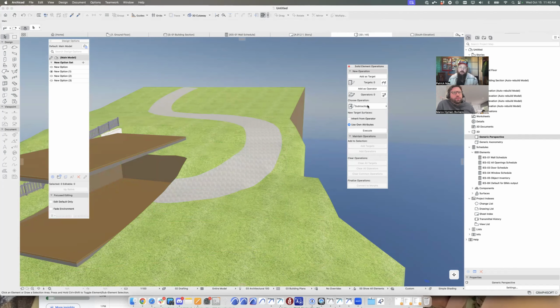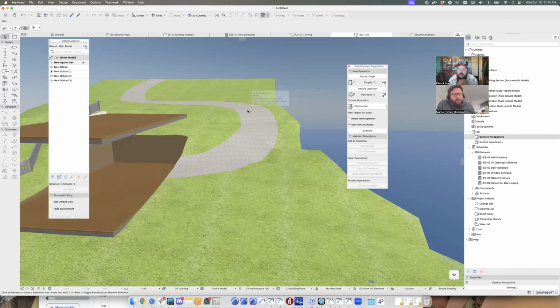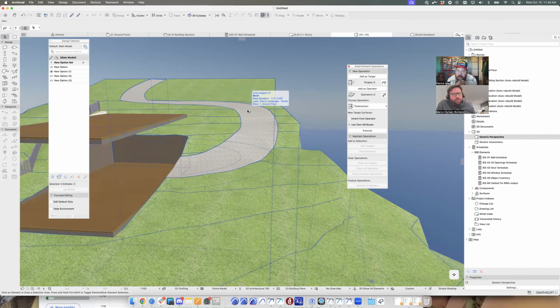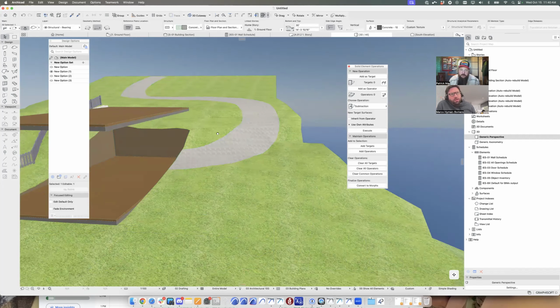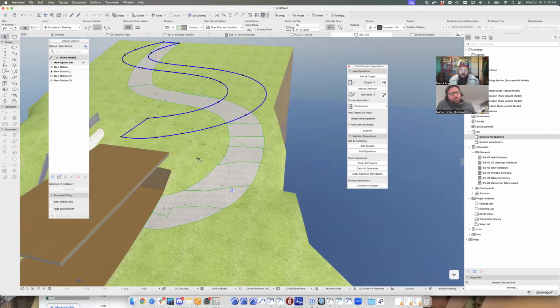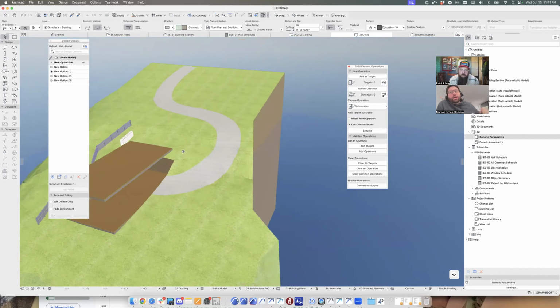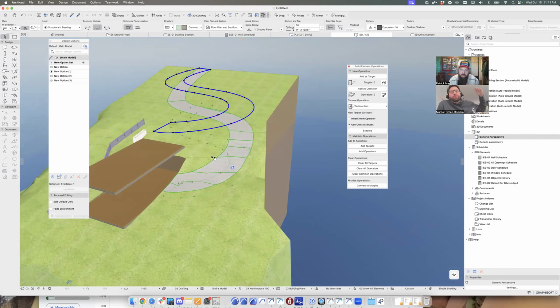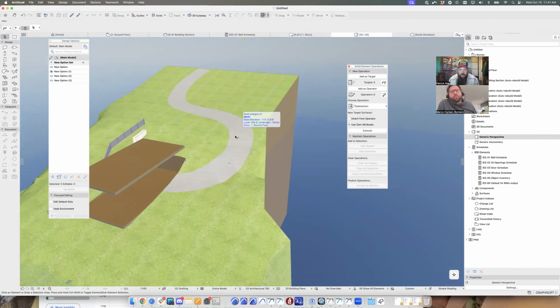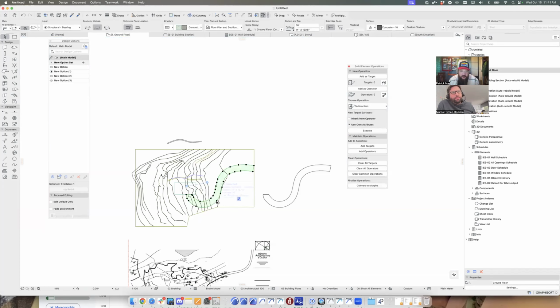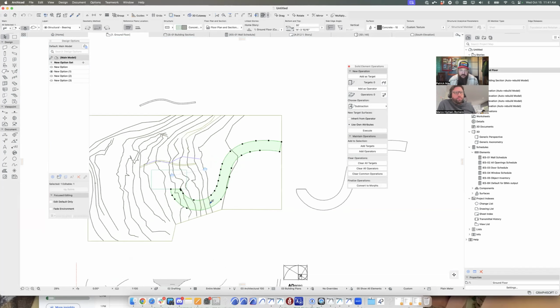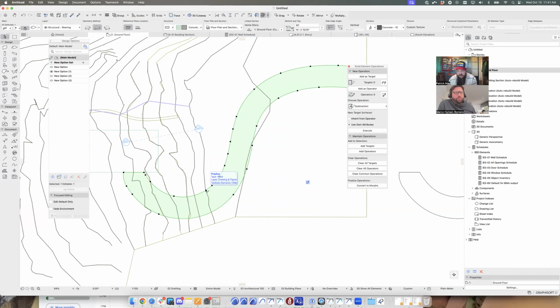So right now the driveway is going to that daylight basement. What if it wanted to actually go to the level that's above it? Like it is built up at a certain point in the terrain and it's arriving at that upper level. To do that, let's say it springs off of this contour right here and goes up to that level. I would actually split it, so use your split command.